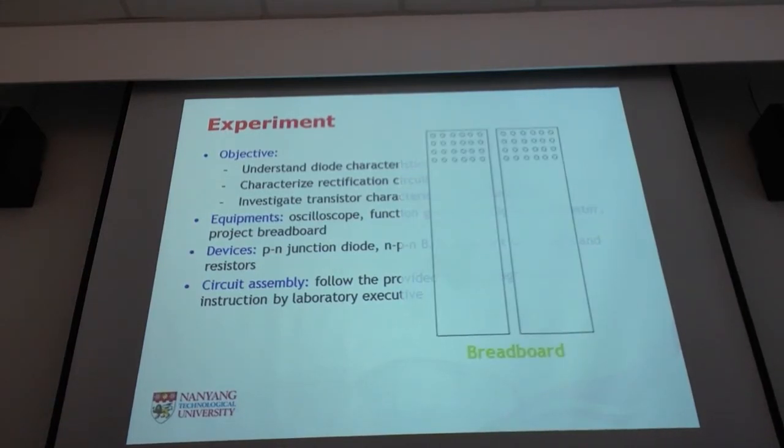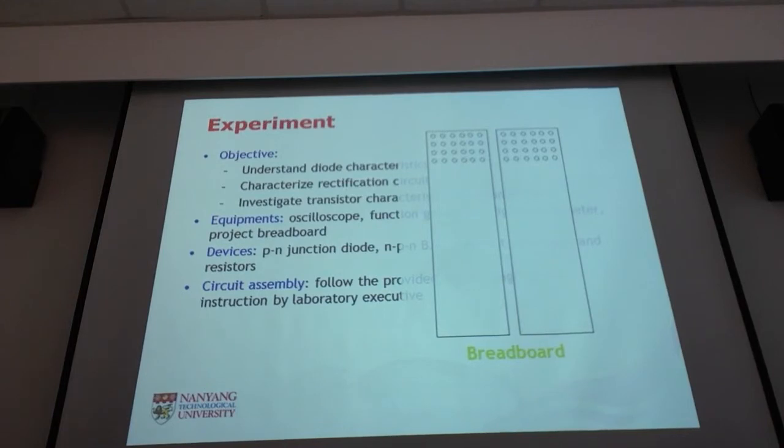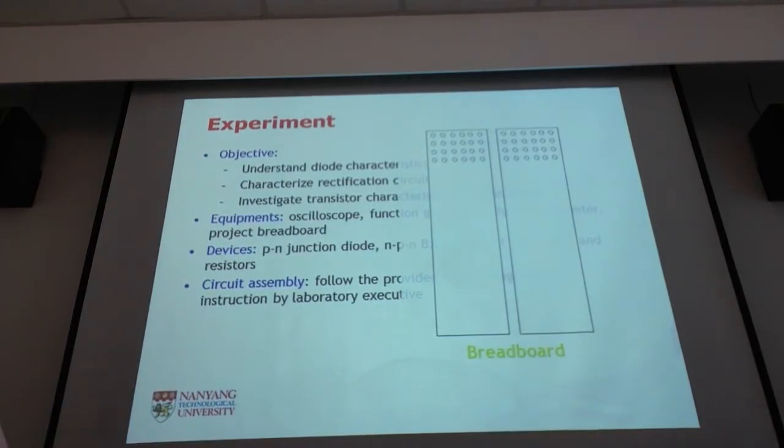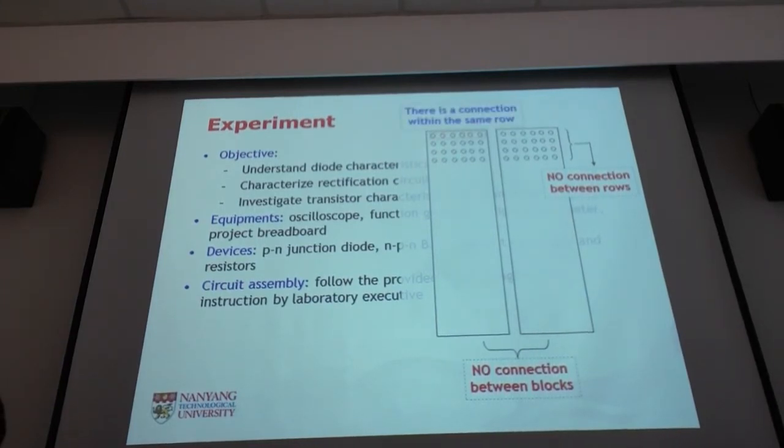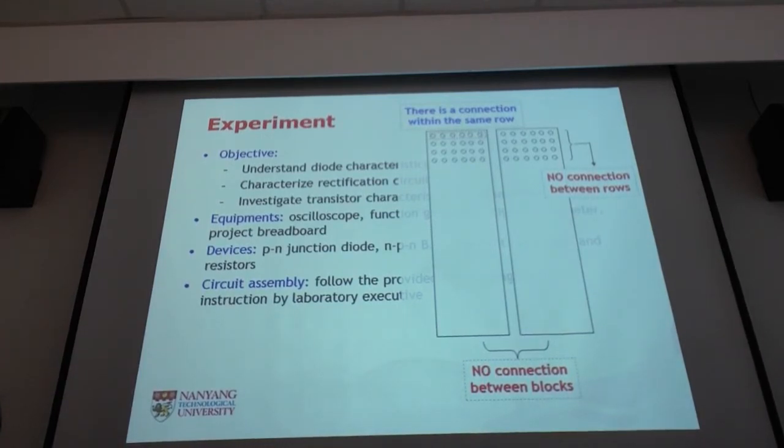Then let's have a look at this breadboard, which is quite new to you, I think. In this case, we have different blocks in one board. Between different blocks, there's no connection. And between different rows in the same block, there's no connection either. The only case that has a connection is within the same row in the same block. This is the only part that you have to remember: within the same row in the same block.